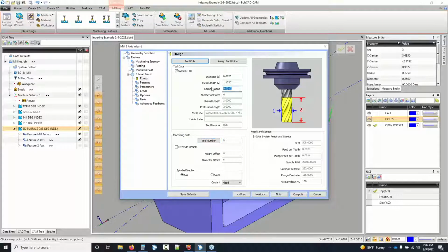So what I always do when I'm setting these up is take the diameter, divide it by 2. That way it is calculating out to really however many decimal places it needs, but then BobCAD's going to truncate it. If I was to go show 5 decimal places instead of 4 right now, that number would show 0.03125 instead of 0.0313. Yes, it could also be a good idea to increase the digits.